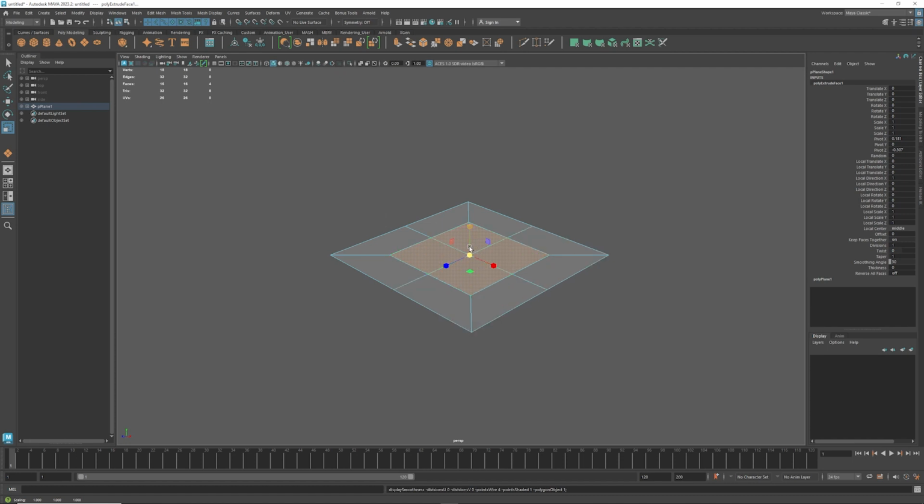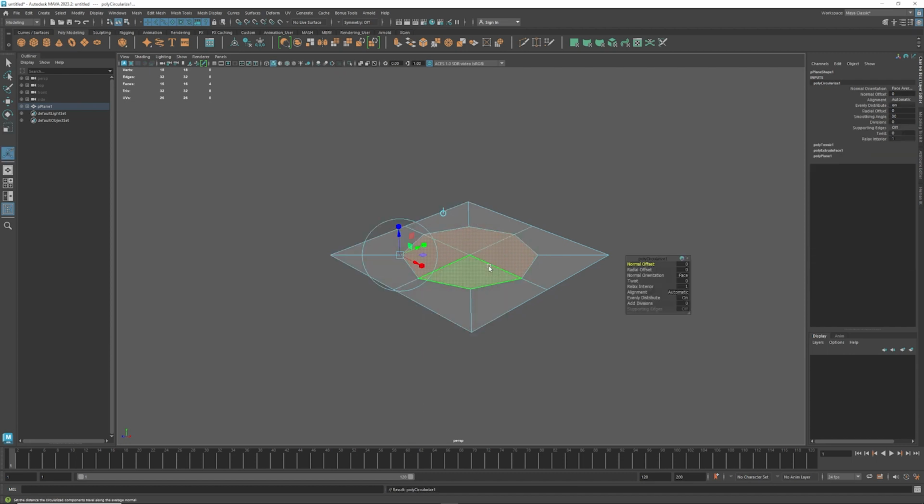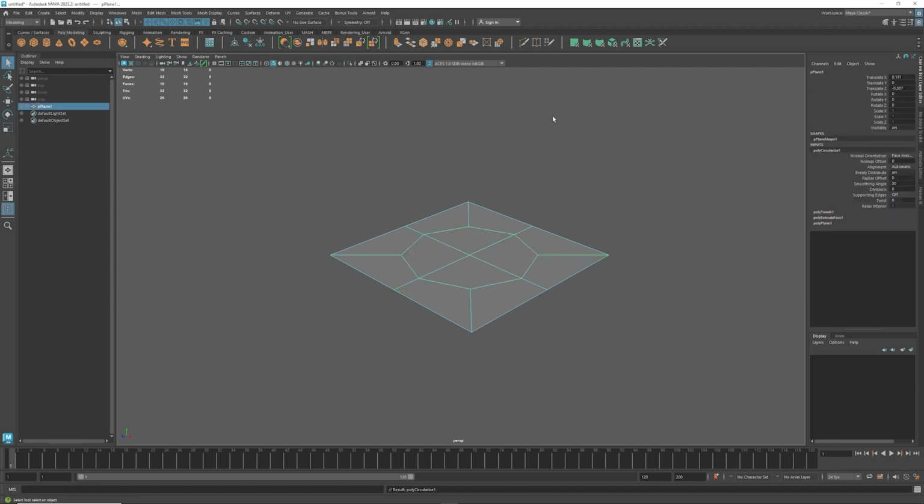And then what I'm going to do is I'm going to right click, and I'm going to go circularize. So circularize is basically going to give me the component that I need to basically build that up. Now, these little blocks are a radius of 2.4 centimeters. So I'm going to just go off of this here. I'm going to go into object mode real quick here.